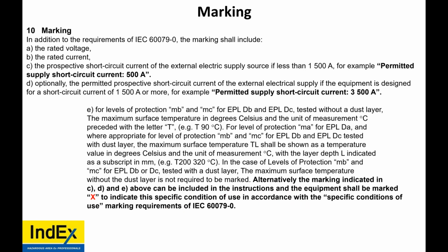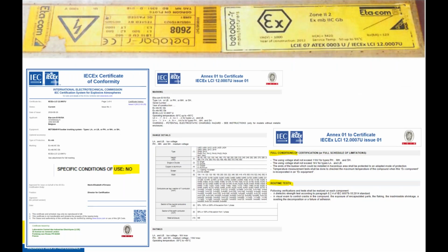Where do you find instructions? Well, the manufacturer's instructions. Certificate, IOMs, then the standard. Where's everything marked? You compare the EX data plate to the data sheet and to the certificate. If you are doing inspections without a data sheet and the certificate and the IOMs, comparing them out in the field, visually proving it, you are doing inspections incorrectly.